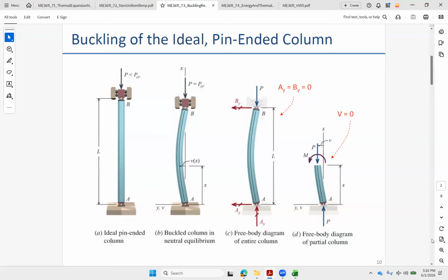That means we're going to be in a pure bending case like we derived the beam theory from. So in that pure bending case, we don't have any transverse force. We won't have a V of X on there. And we've got P pushing on both ends. If I take a slice through this anywhere along the inside of the beam, I cut it, I'm going to have some bending moment. And then if I've got X this way and Y this way, my Z is going to be this way. So my moment, with my right-hand rule for Z, is going to be like that.